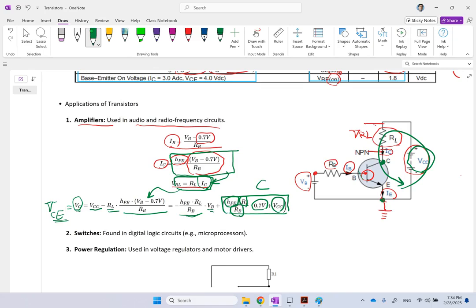VB is the voltage that you have behind the base, and this guy here, that is a gain. So you can call it whatever you want, call it gain G. So you see that voltage of point C with respect to the ground, or E in this case, is equal to negative G times voltage of B with respect to the ground plus some constant.